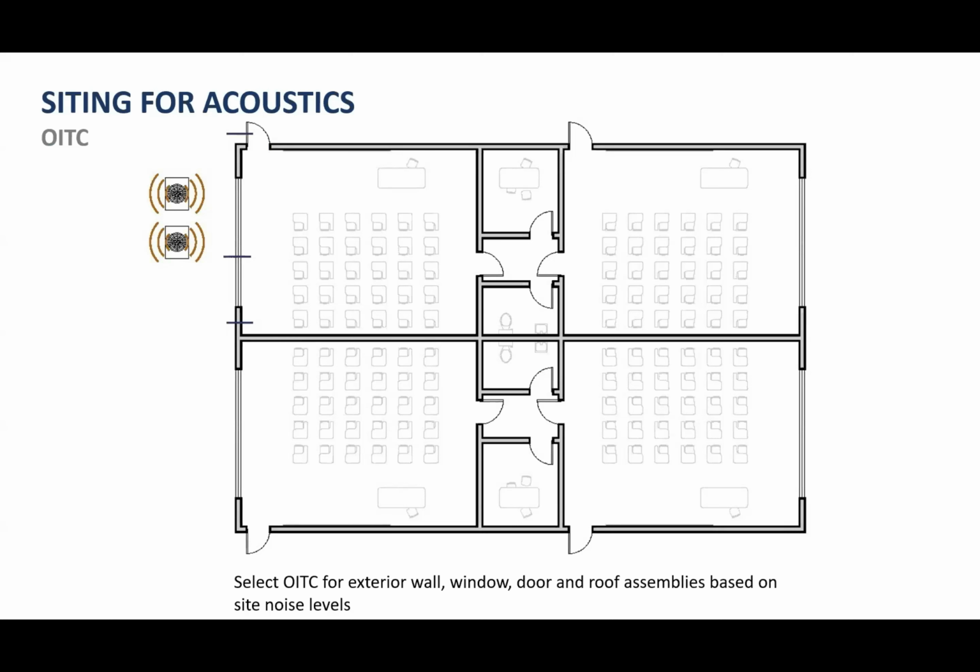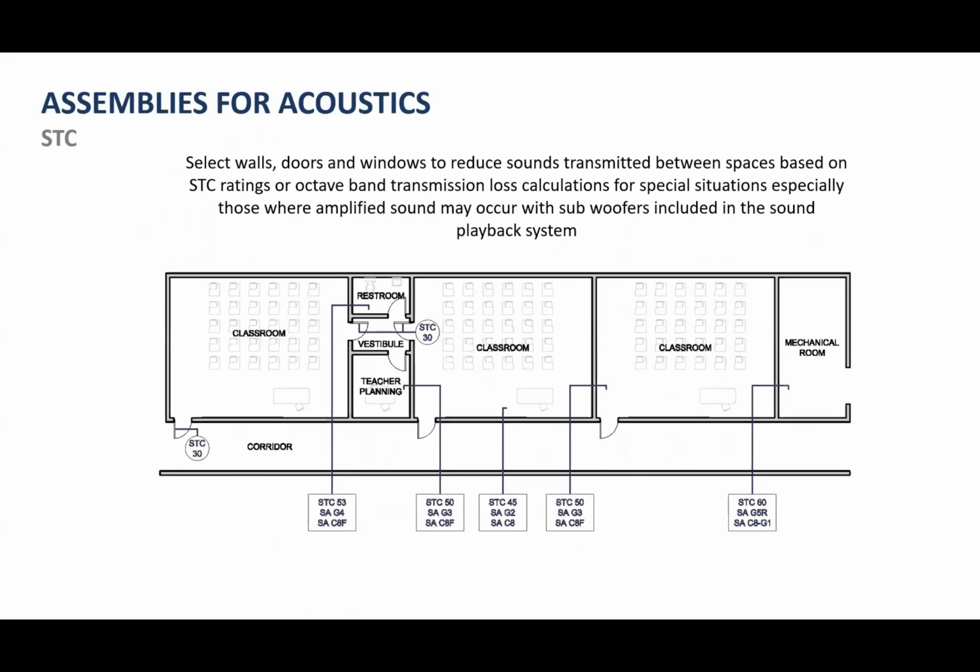And this is something that goes along with doing a noise study on the site, a noise survey, where we're measuring and documenting sound levels to really figure out what are the sounds that are anticipated on the site? What levels are they? How frequent are they? Are they something that's going to impact the site, or is it a fairly lowly impacted rural site? So just some things to think about.